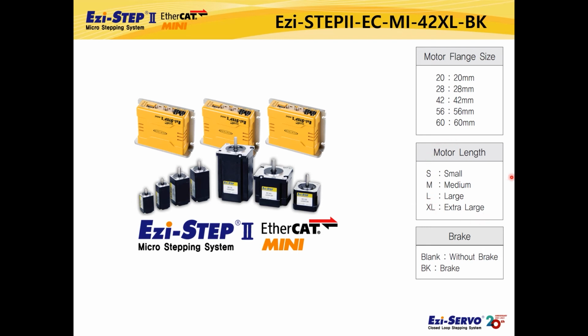Motor length is the length of the motor body excluding the motor shaft, and you can select small, medium, large, and extra large length. The lengths you can select depend on the motor size. A brake can be applied from a NEMA 17, 42 mm size motor, to a NEMA 24, 60 mm size motor. The brake is a non-excitation type that activates when the power goes off.